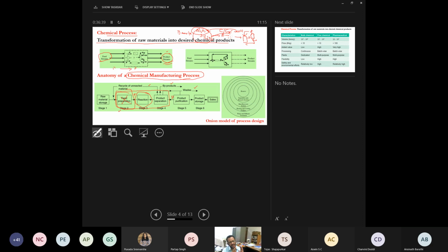So the sodium aluminate is cleaned by the water, so it is diluted. Normally this sodium aluminate and water will go in countercurrent manner. Finally you will get this sodium aluminate. Then it has to be sent to the filters to remove the fine particles like Fe2O3, those things.